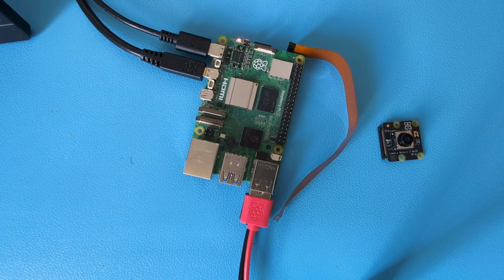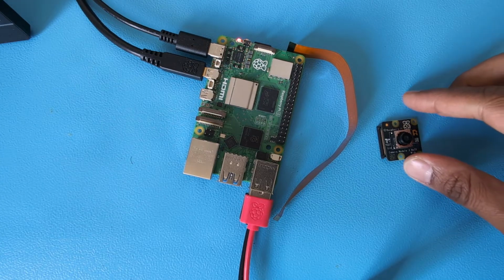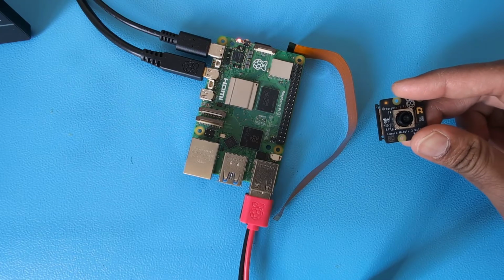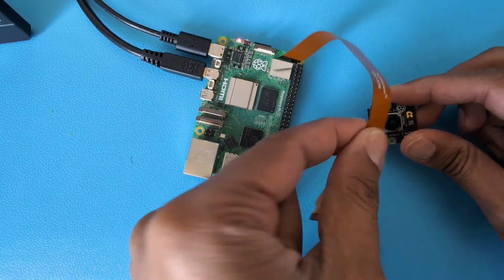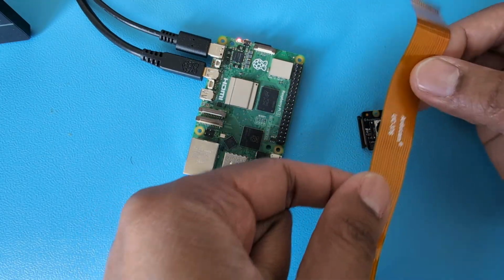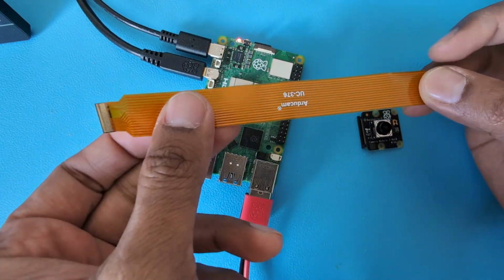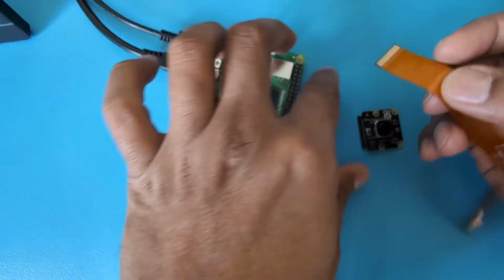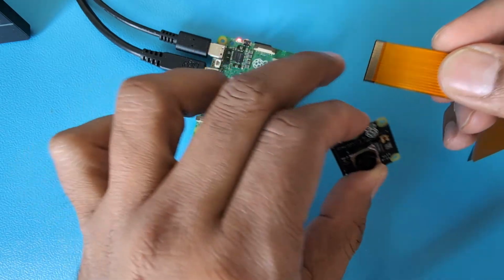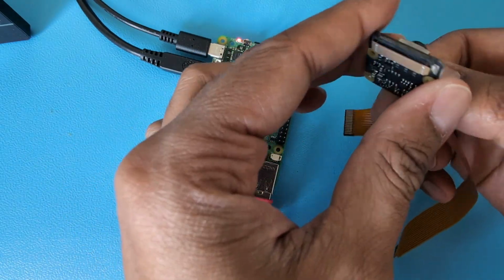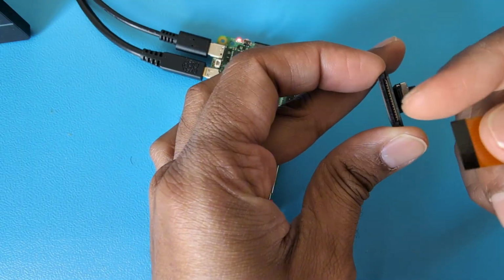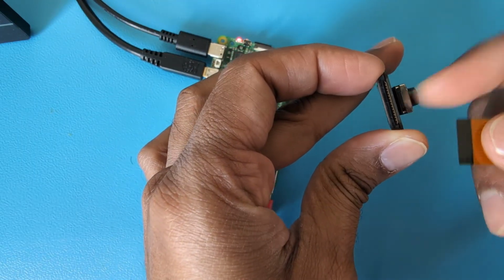So now I'll show how to connect the camera to the Raspberry Pi 5. We'll use camera module 3 wide version for Raspberry Pi. And here we have the camera cable, which is mainly 15 pin to 22 pin CSI cable. So to connect the cable to the camera, you have to look carefully at these pins, and here you will have to look at this part where the pins are coming out.